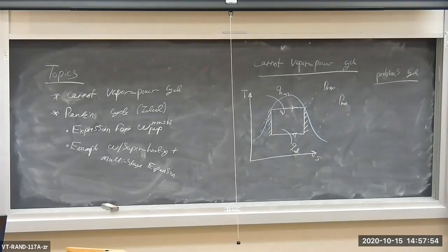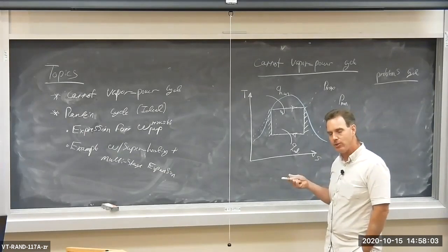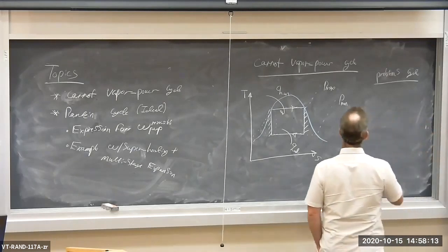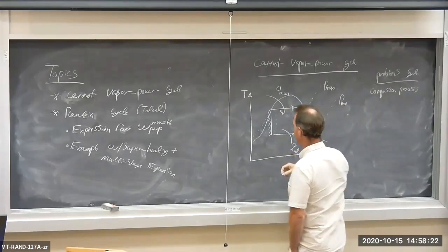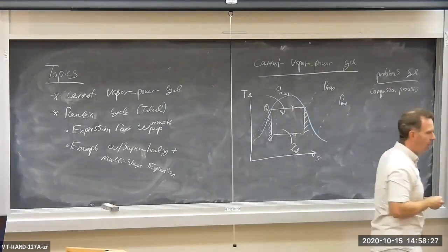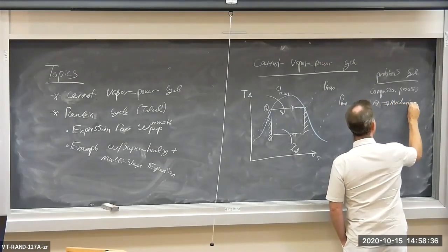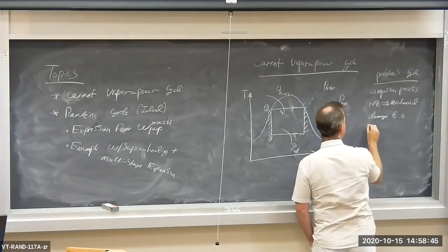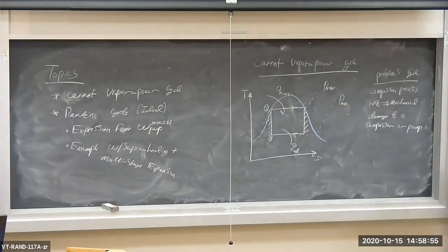Now, most mechanical devices, open flow devices, do not like mixtures of H2O, of a liquid and vapor. A compressor is made to compress a gas, and a pump is made to compress a liquid, and there aren't really any good devices that handle both together. So the compression process from state 1 to state 2 will result in significant mechanical damage to a compressor or a pump, because we have a mixture of the two. A pump is meant to pressurize liquids. A compressor is meant to compress vapor or gases, okay?